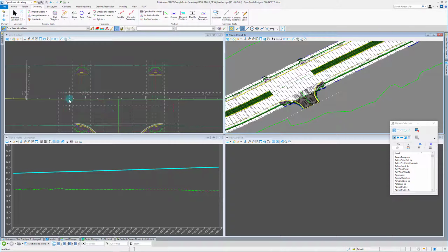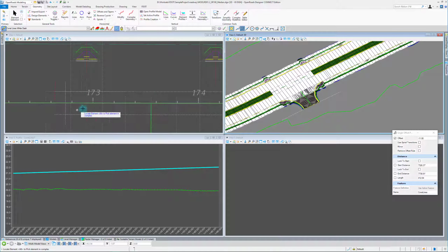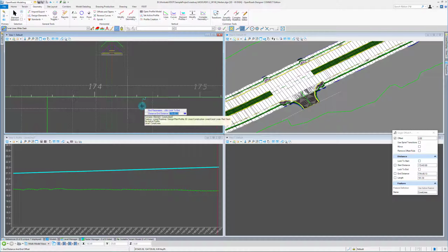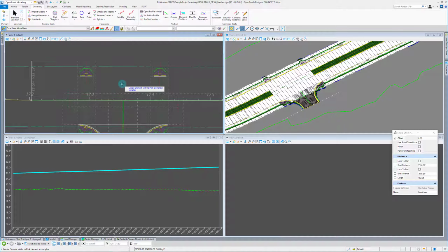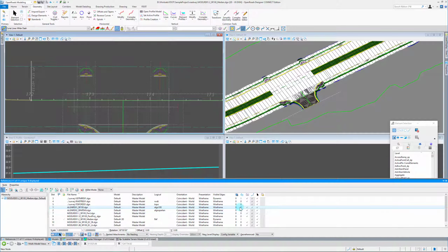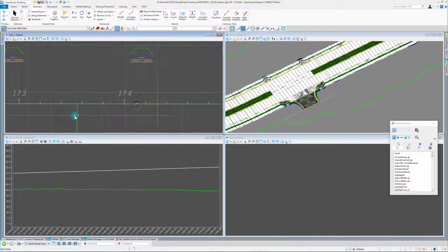And we need to set up one more line, and that's right down the middle, because that's going to be basically our crown of our pavement down the median. So we'll set that up, and we really only need that to go to here, because this is really going to be for our detail modeling only. And to make sure I can see that a little better, let's set the priority of this to -1. Hopefully that will make that show up a little better.